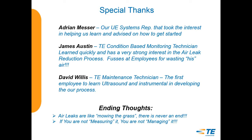One of the things that we publish in our compressed air guidelines is we don't use any galvanized pipe, mainly because eventually moisture is going to get in those and it's going to rust, and the rust is going to get blown on down the system. So, the SMC and the Festo, that's just a couple of our vendors that we use because we use a lot of their stuff. And it seems to be fairly reliable and holds up good. The biggest issue we really see with fittings is people trying to marry up metric and standard, and in 90% of the cases, it just does not work out very well.